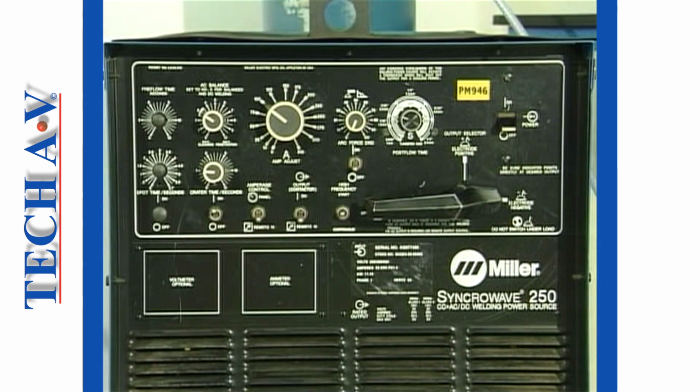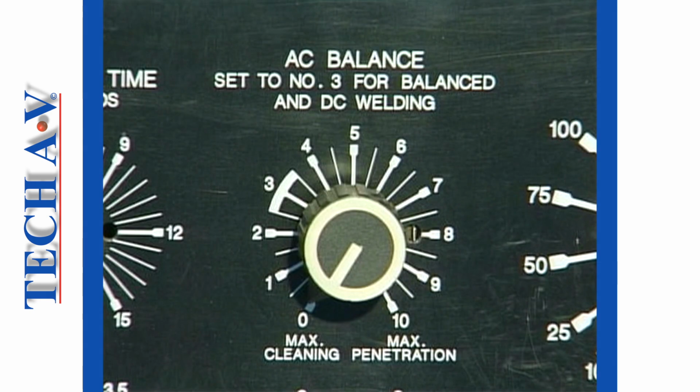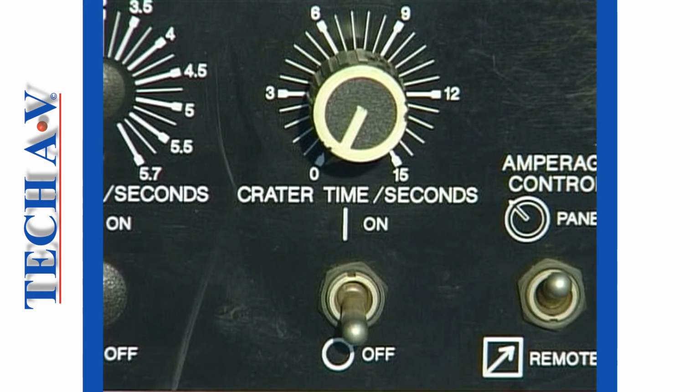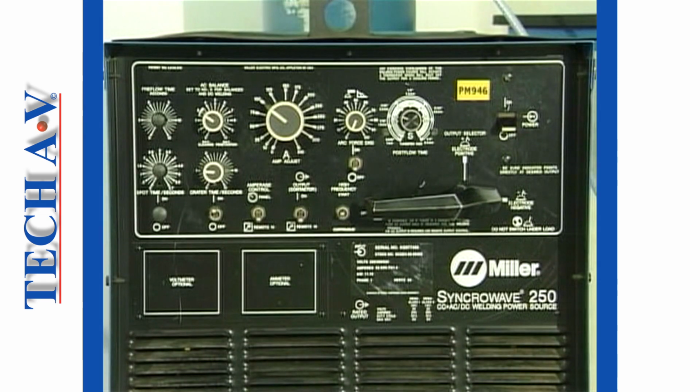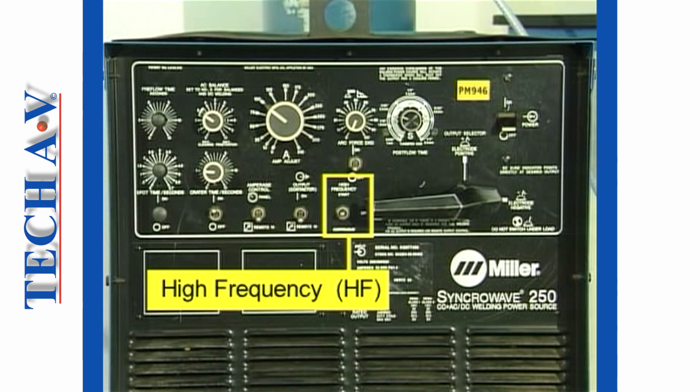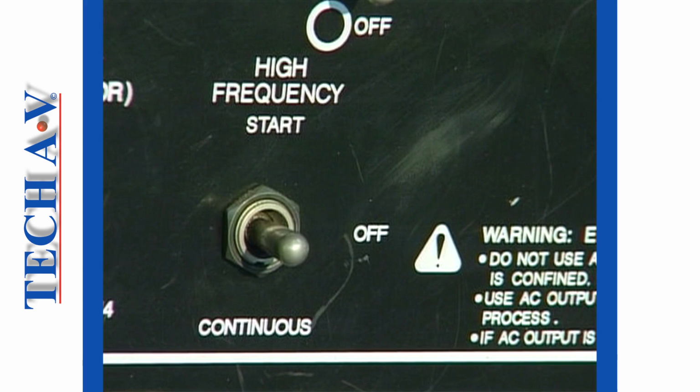The following controls and selection devices will depend very much upon the make and type of machine that you have. One important control is the HF or high-frequency switch, especially if you intend welding aluminium. This particular machine uses a three-position switch with the off selection being in the center position.